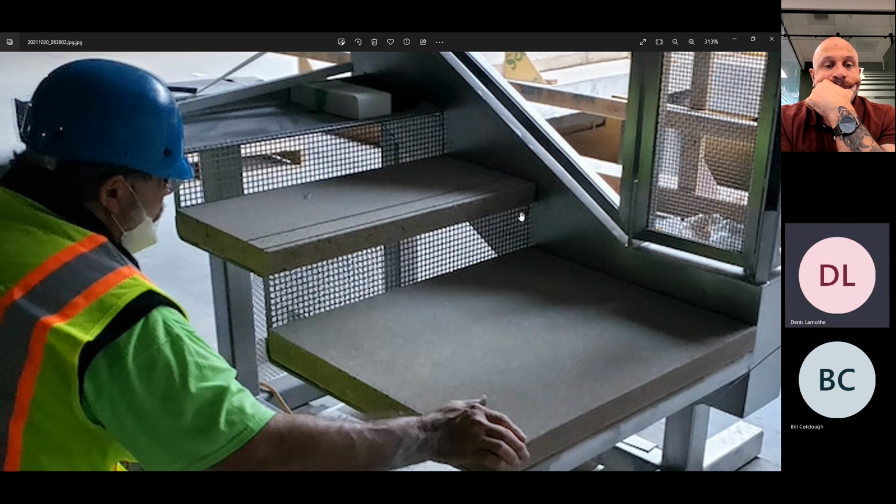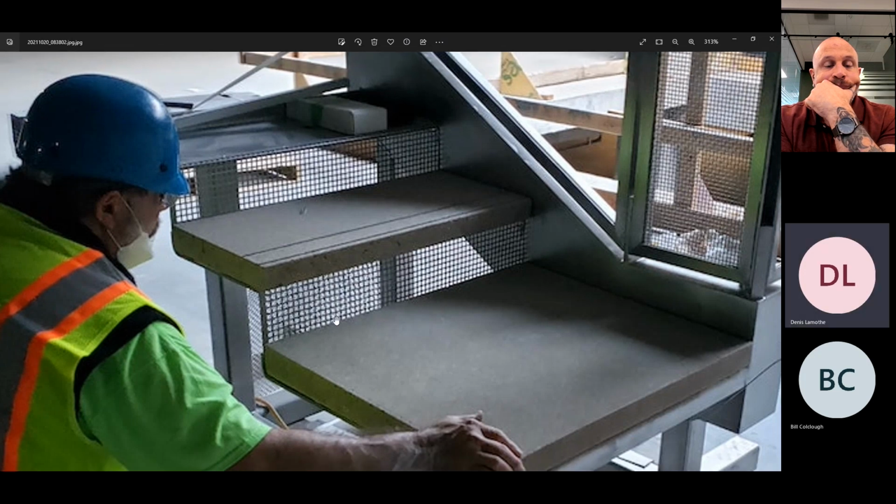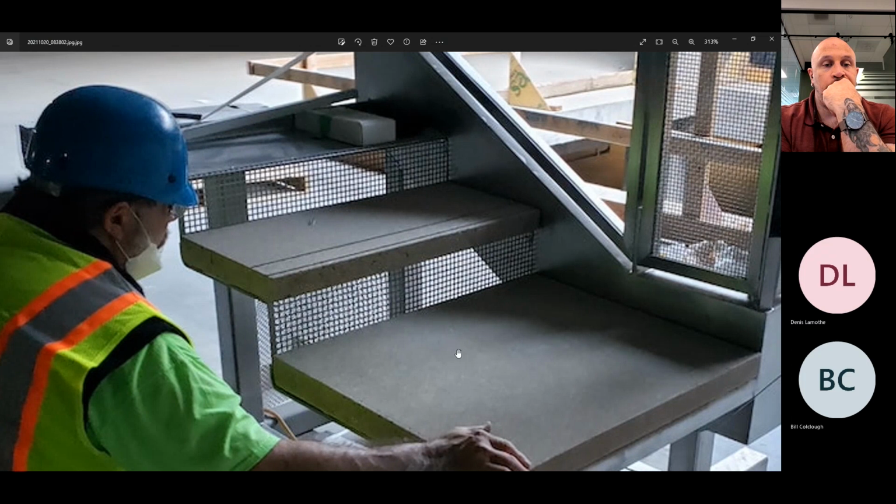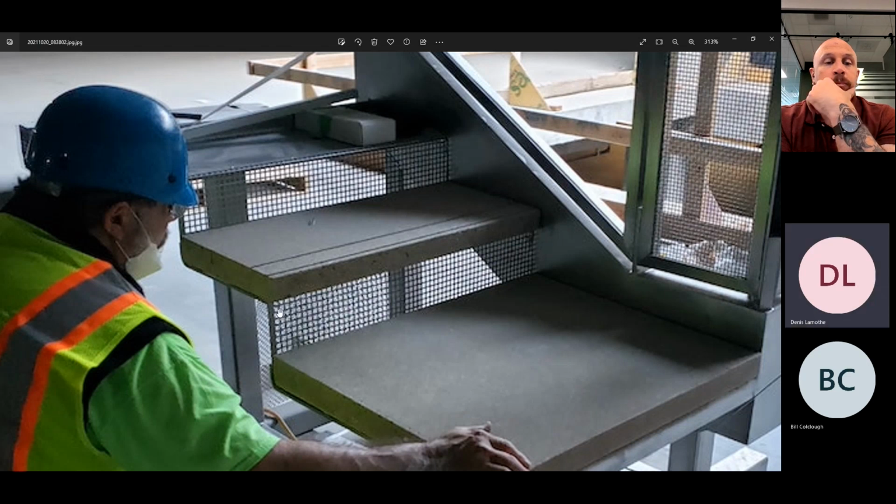Most stairs that we work in, the openings could be really minimal, so that it makes it less obstructive to the view. Yeah. So we will often work with perforated panels. Usually it's a solid panel of some sort, or it could just be a wood finish applied to it. We've occasionally worked with some glass panels in the risers, and those would have a film applied to them. It could also be like an acid etched or a bead blasted kind of look, just to make that glass cloudy, and therefore you can't really see through it.